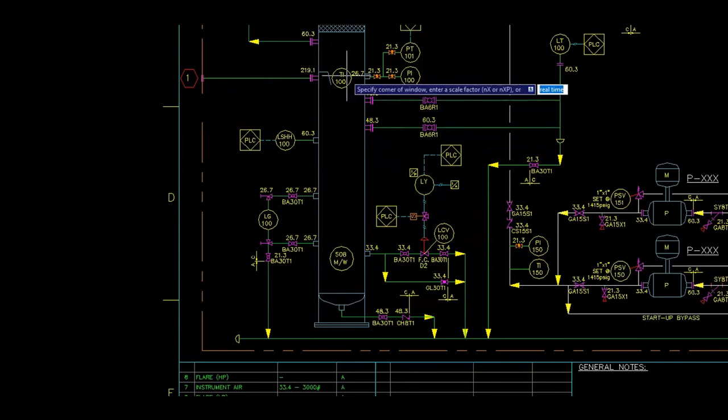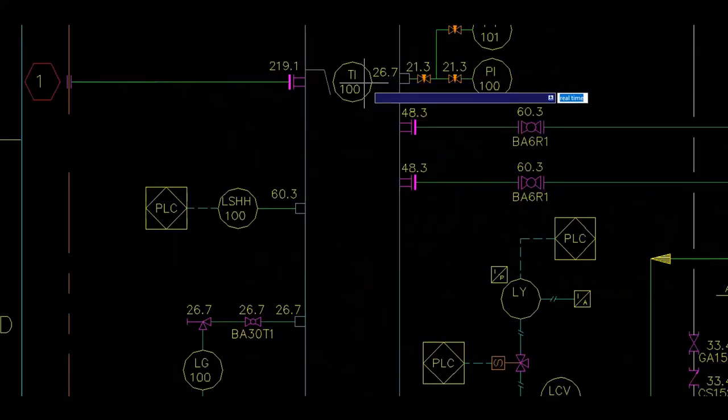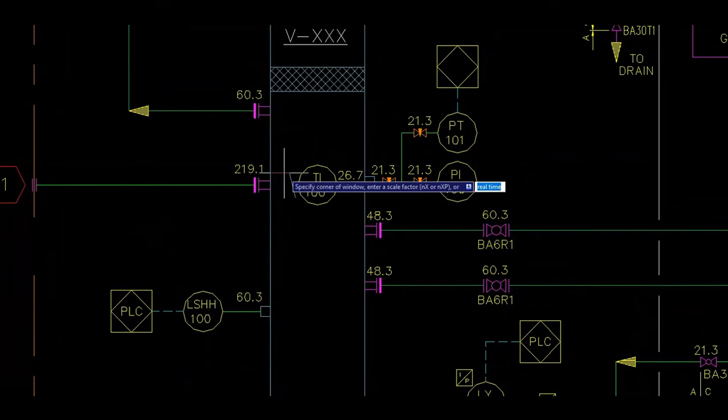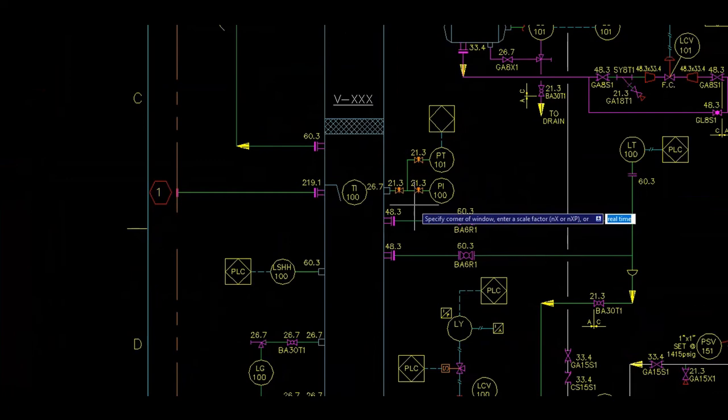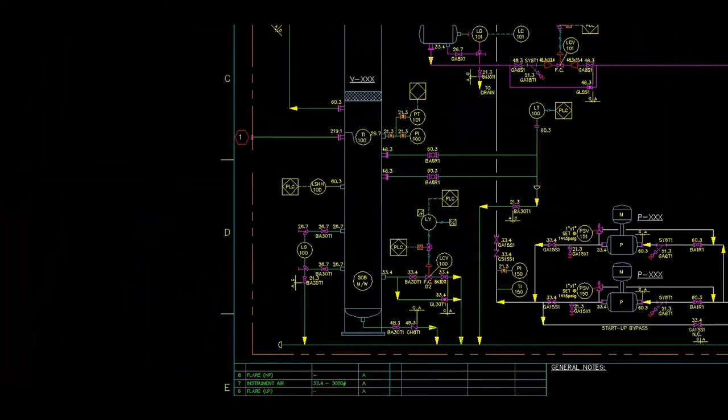Since the gas is saturated at the temperature, when water impinges on the inlet deflector here, the equilibrium will break. The mechanical collision will break the equilibrium and liquids will break out of the gas phase. This piece of equipment right here will lighten the load of drying on the part of lean glycol. Throughout the design of this package, you will notice how units are placed in series to lighten the load of downstream equipment so that dew point is achieved.